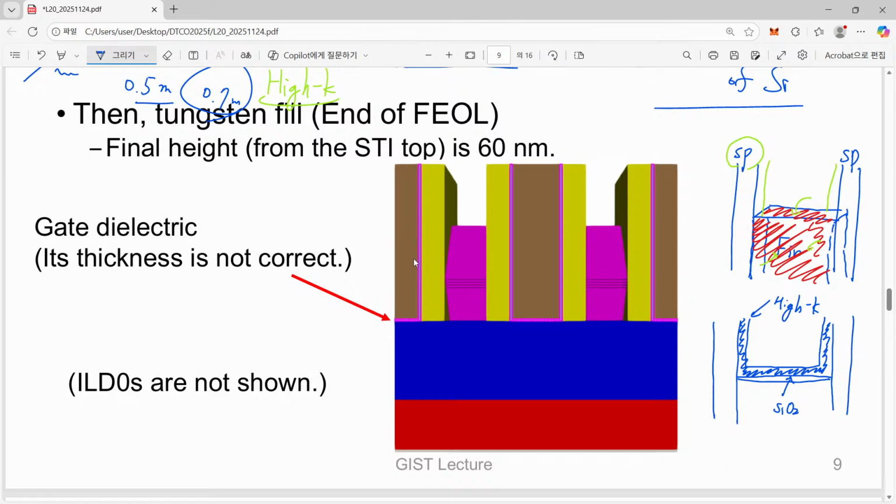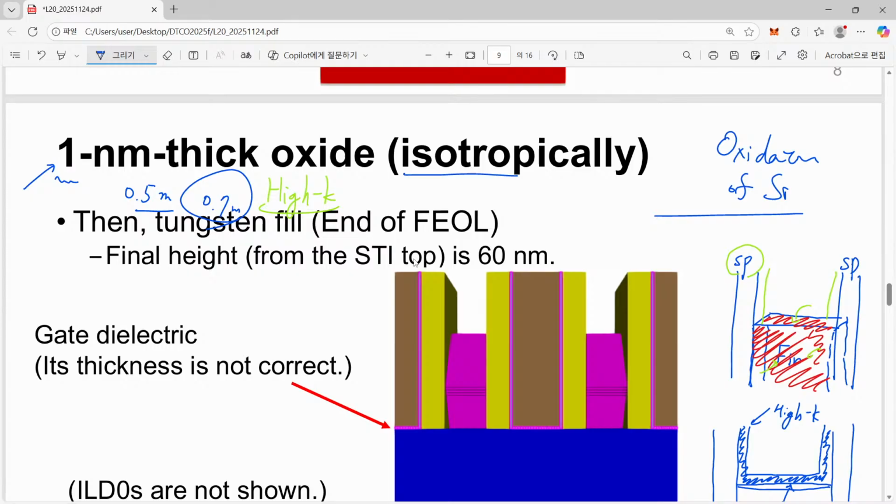But you know, high K materials do not contribute a lot of effective thickness to our transistor, because although we have an EOT around 1.0 nanometer, slightly shorter or slightly longer, most of it, or a considerable amount of it, is consumed by this intrinsic silicon dioxide.